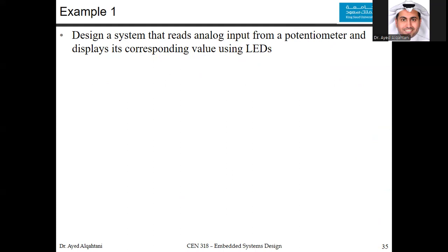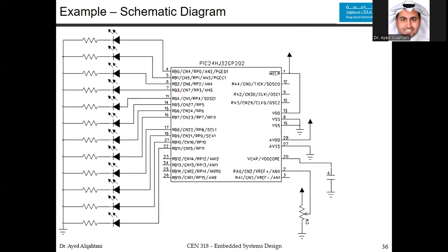To do this, we need to do interfacing and program. For the interfacing, we choose the RB board from RB0 all the way to RB15. So that's 16 bits that we can choose from. And we have only two choices for the resolution, either 10 bits or 12 bits. Here we choose from 0 to 11. You see that they are connected to LEDs, and after the LEDs, we have resistance. So we actually chose 12 bits in the connection of port B.